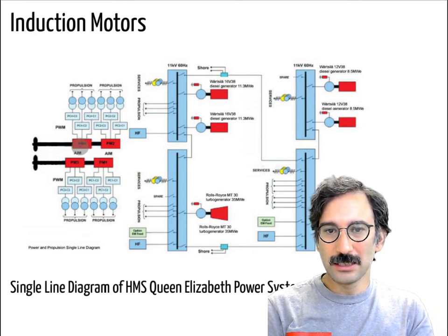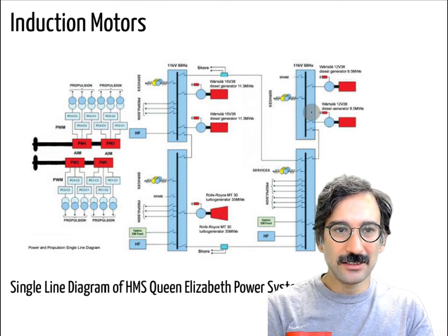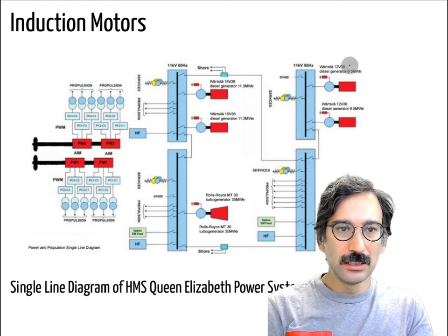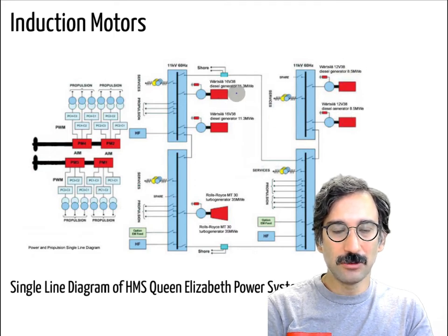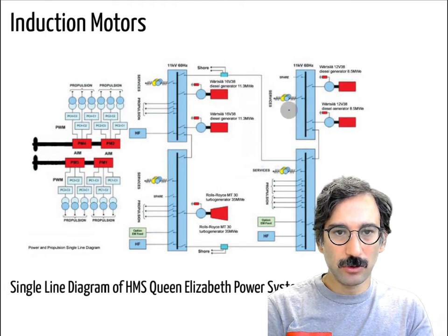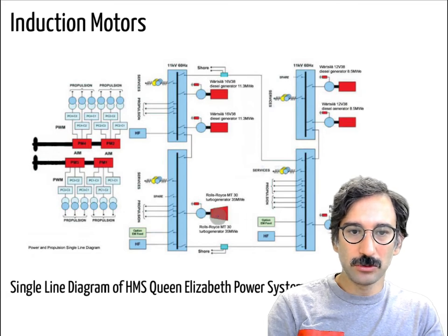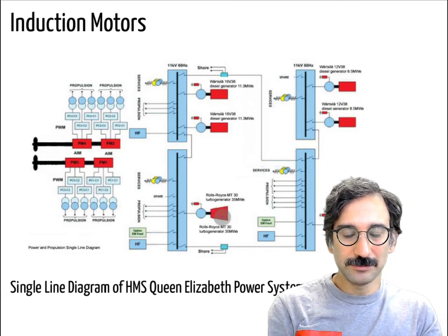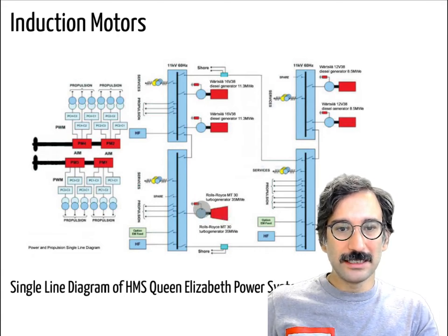You can see that one of those motors is driven through 3 different transformers and controllers. The energy is coming from, I don't know if you can see that, 1 2 3 4 diesel generators. These are 8.5 megawatt, these are over 11 megawatts. But these are just auxiliary. The main power is coming from turbo generators, again using some fossil fuels to run a synchronous generator.